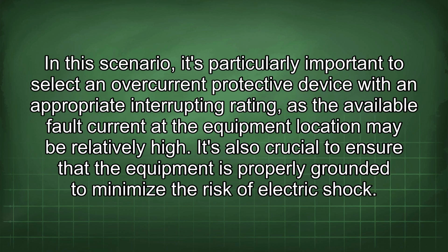In this scenario, it's particularly important to select an overcurrent protective device with an appropriate interrupting rating, as the available fault current at the equipment location may be relatively high. It's also crucial to ensure that the equipment is properly grounded to minimize the risk of electric shock.